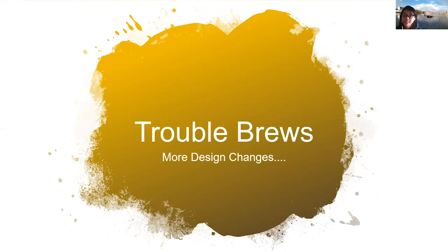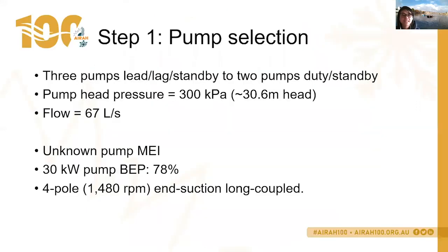So instead of lead, lag, standby, we're now only doing duty standby, which means that at the plant room level, instead of 35 liters per second, now I need to have a flow of 67 liters per second. And my pump head pressure is now 300 kPa, just because there's been increased pressure losses in my plant room itself associated with the fittings.